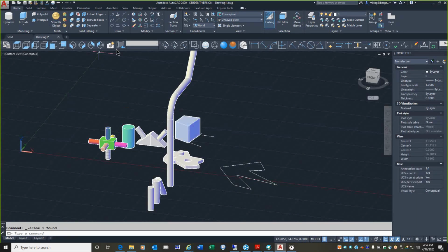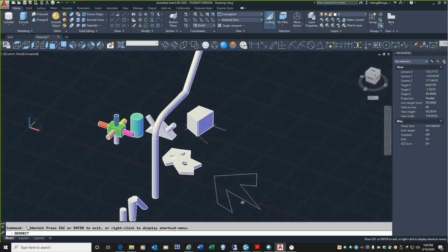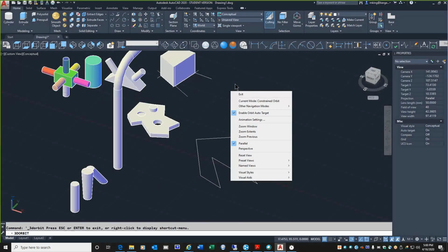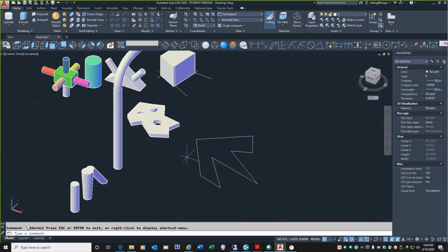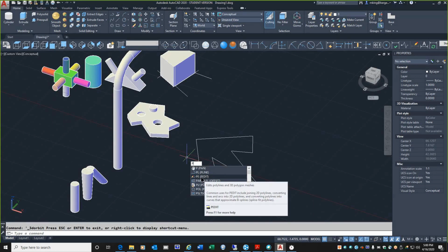So now that I know it's a line, and I need that to be one continuous solid shape, what do I do? Well, what we learned a few classes ago: I polyline edit and join it to become one continuous shape. To do that, I type the letter P, and you can see right away the autocomplete popped up, so I'd select PEDIT.